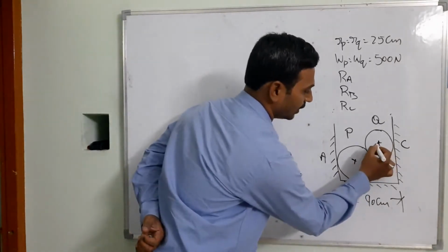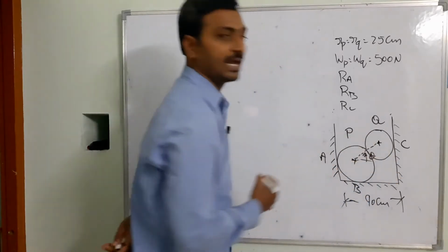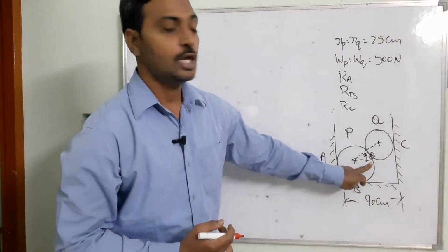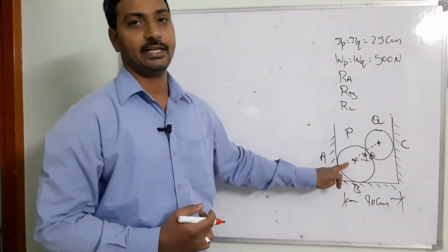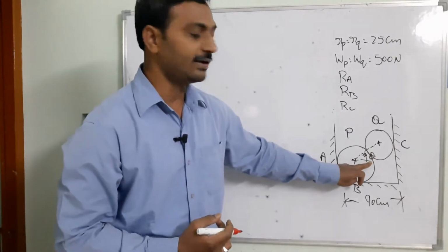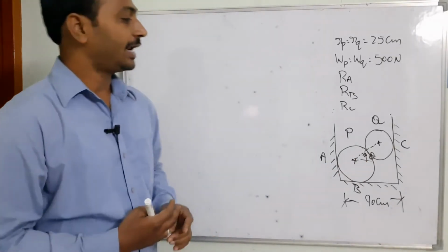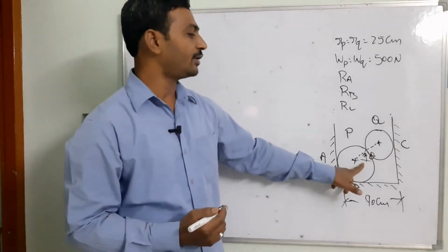Can you see, what is the inclination going to be? This theta I need to calculate. If I calculate the theta over here, then I can easily calculate the direction of your reaction force. If I do not find the theta, then it is going to be very difficult to follow which direction it is acting exactly. For this one, I am going to try to find it out over here.